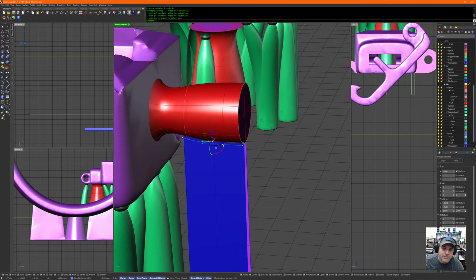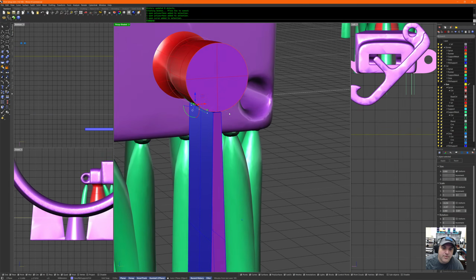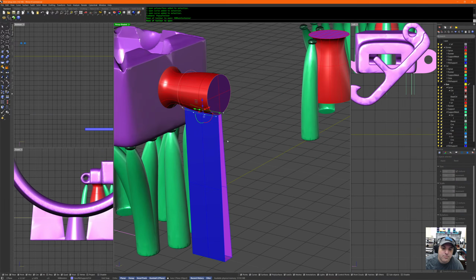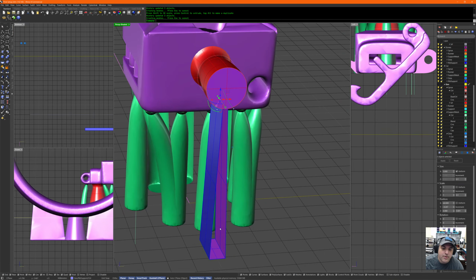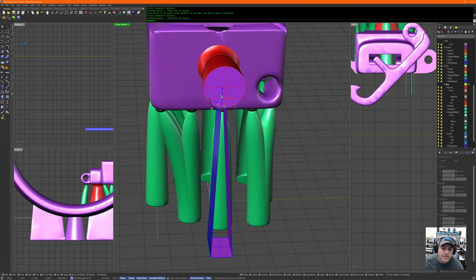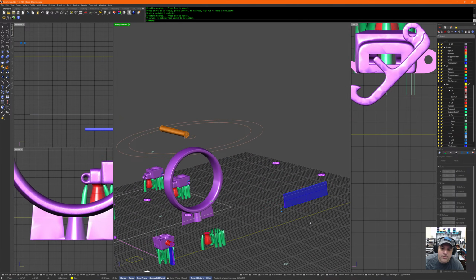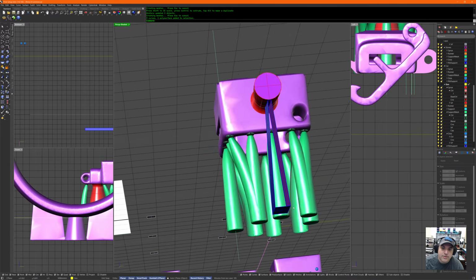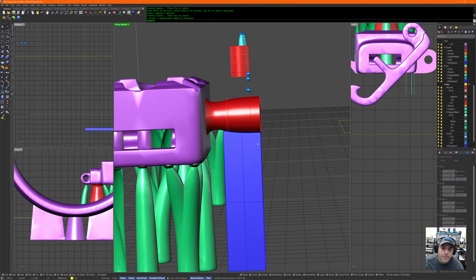Now I have this right here, where if I don't think this taper is enough, I can take these two curves, break them, and scale them apart a little bit and get a base that's a little bit wider. And if I don't like it, I can go back and start over from there. But that does look like a good rib support to put on the sprue.